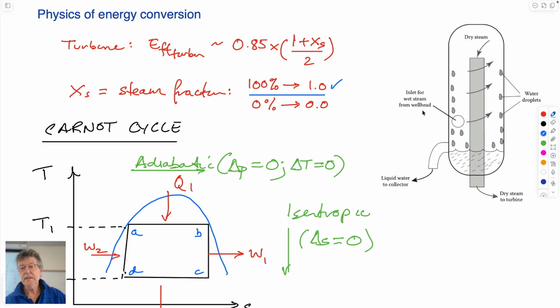So this idea is here. It goes into a steam to water separator. It comes in at some mid-level. The steam buoys to the top and then is taken out to the generators. The water sinks to the bottom, is siphoned off and is re-injected or maybe run through a binary plant.